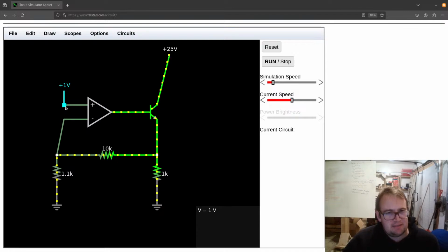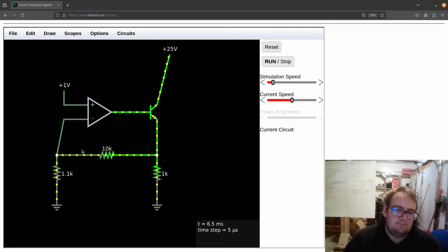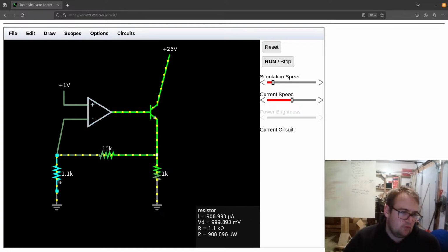Because we applied 10 volts here. And just imagine this isn't there, this 1K isn't actually here, and this transistor isn't here. We just start connecting right to here. So that means there's going to be 1 volt applied here, because we have to have 1 volt there. So if there's 1 volt applied here, then there's about a milliamp going through.